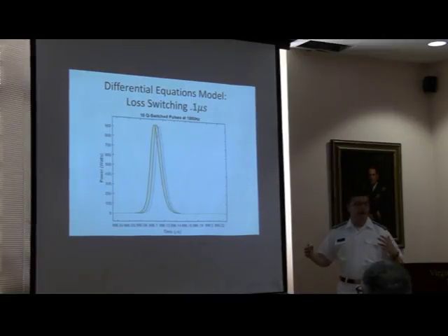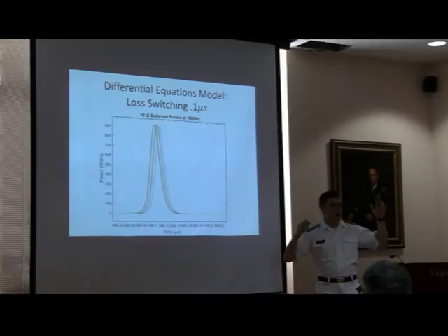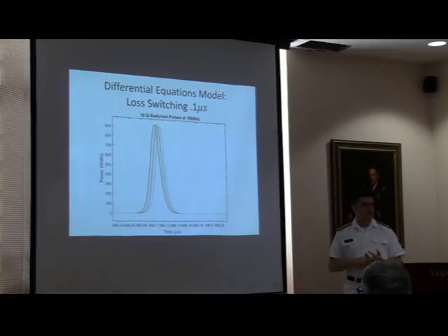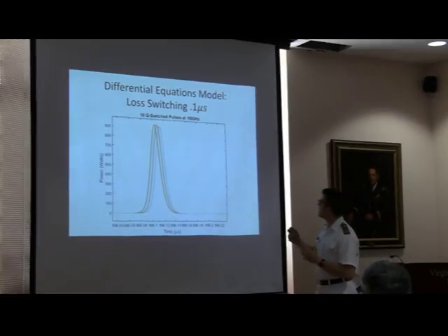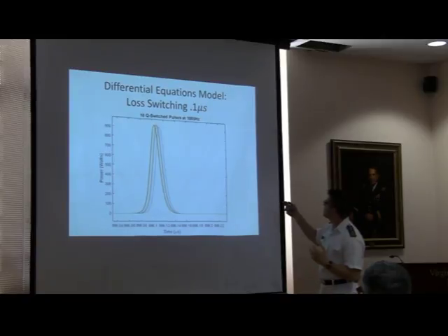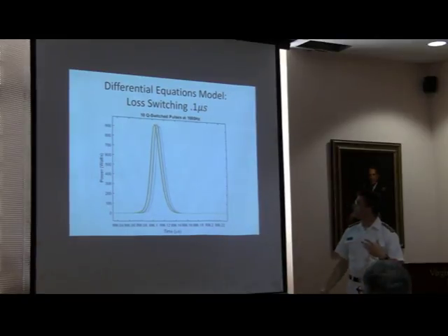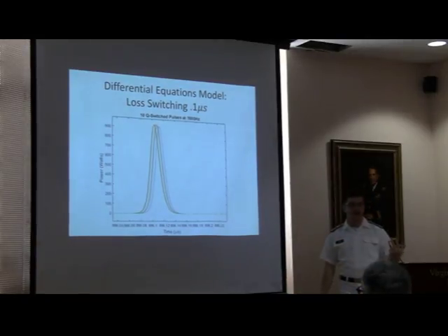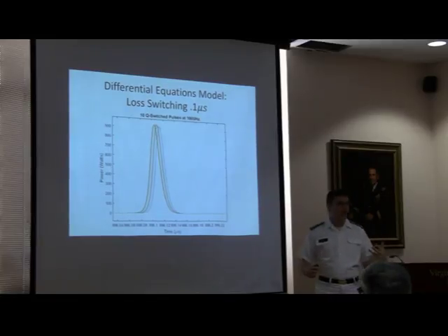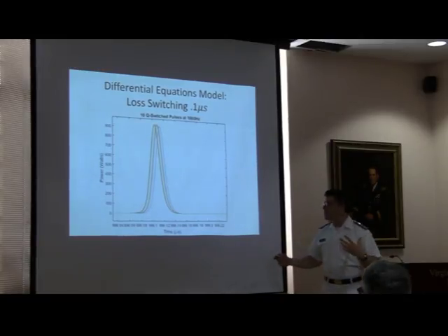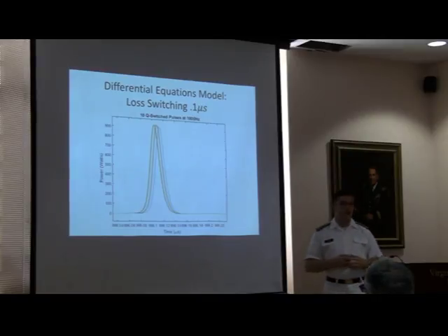But there are also effects on a much more macroscopic scale, on pulse ensembles, not just single ones. We see that with changes in switching time, we see a change in how fast the transients die out. The transients are not permanent. It's just the first couple, 10, 20, however many pulses you have that decide to not really settle in at the beam of the laser. And generally, with the lower switching time, you have quicker dying out transients.